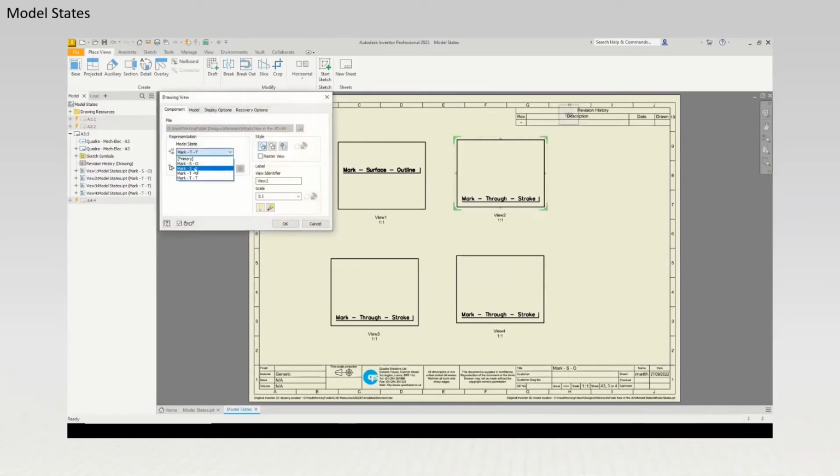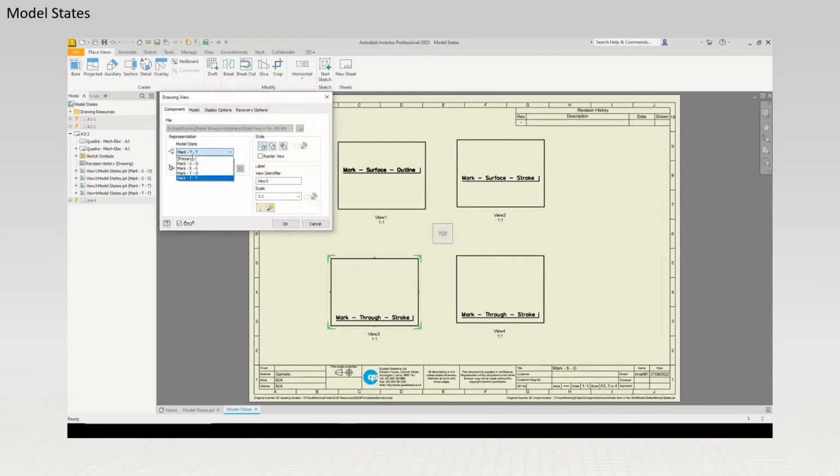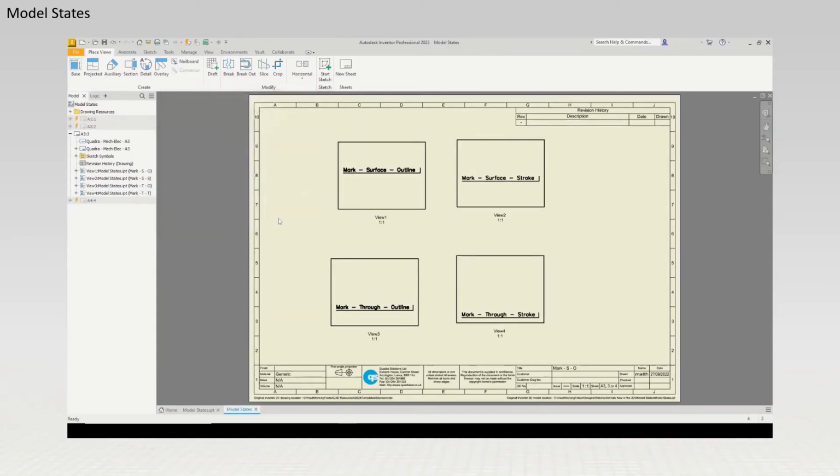In this particular case, I would now have 1, 2, 3, 4, 5, 6 files: the master, the primary, the factory iPart, the drawing, plus 4 variations of that particular iPart. So I'm already saving myself a fair few files in the background that don't need to be managed.